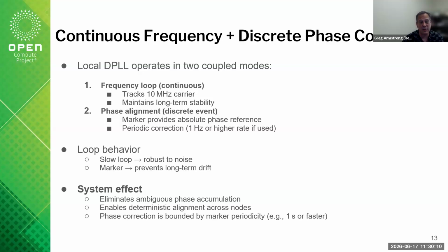So effectively, a lot of people would have to lock to it and try to synthesize a clock that has exactly 10 million or 10 billion cycles of clocks before the next edge, and try to maintain that synchronization only looking at that 1 hertz signal. Well, there's a lot of challenges to that, right? You have to have a very low time constant to be able to lock to it and stabilize that clock. And then also, you need a very stable clock to maintain your local clock, because if it's a noisy clock or drifting a lot, it's very difficult to pull back 10 billion cycles to make sure it's 10 billion every 1 second, right? So there's a lot of challenges trying to deal with a 1 hertz signal.